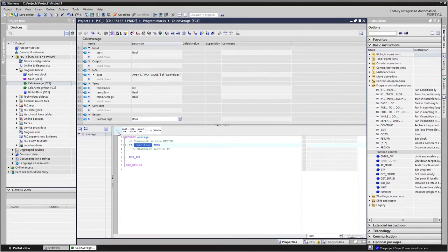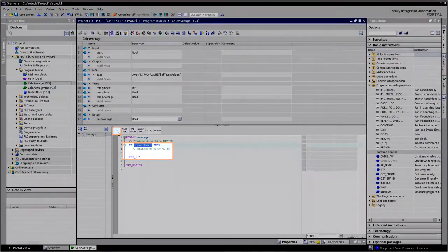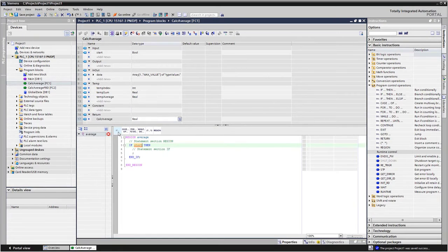With the if instruction in SCL, you can have the program section called up conditionally. The editor adds the full syntax of the instruction. Now all you have to do is replace the wildcard with a condition. IntelliSense supports you in variable selection. Alternatively, you can also enter the SCL instructions manually.